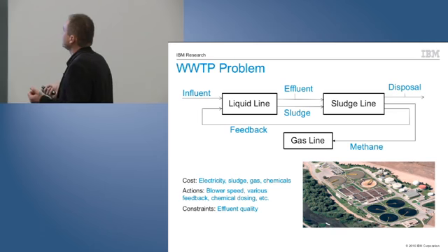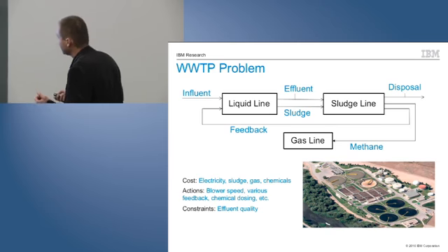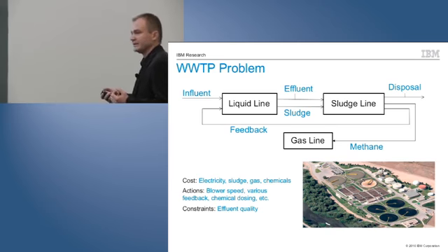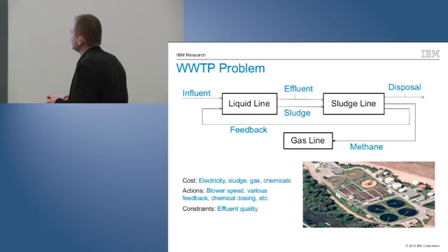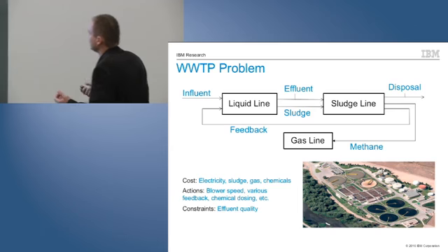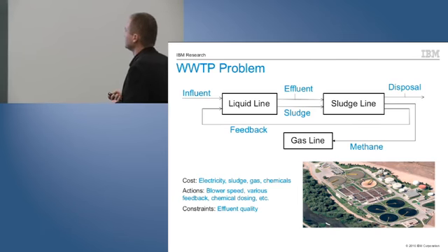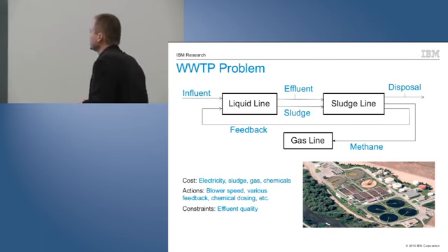As a byproduct of the process, a gas called methane is generated and is coming to the gas line and used as an alternative source of energy. Part of the water is going back to input for additional treatment. Cleaned water, called effluent, is diverted to the close river.